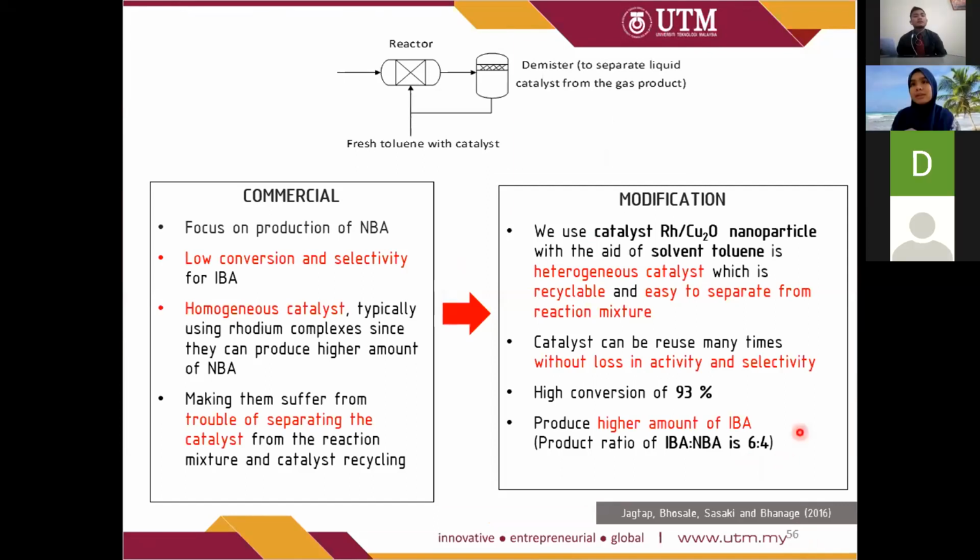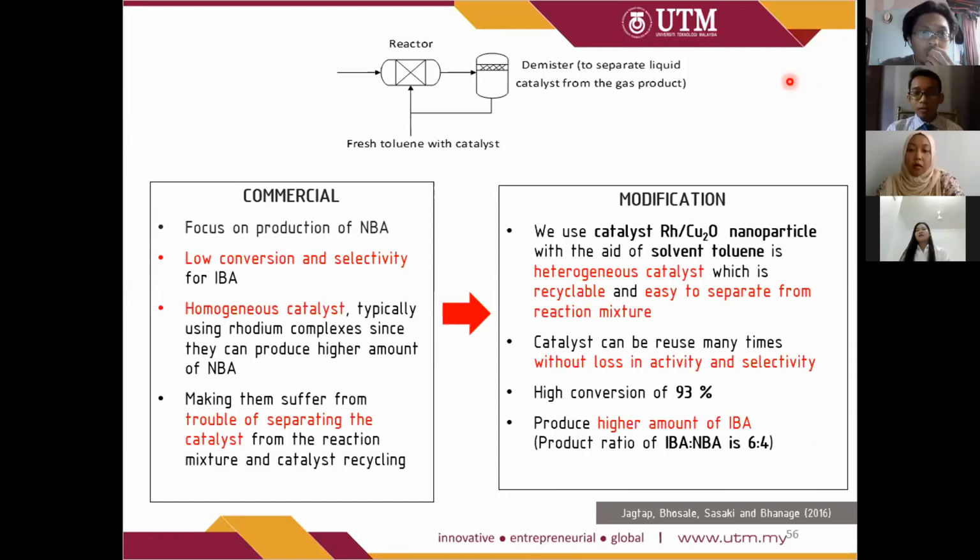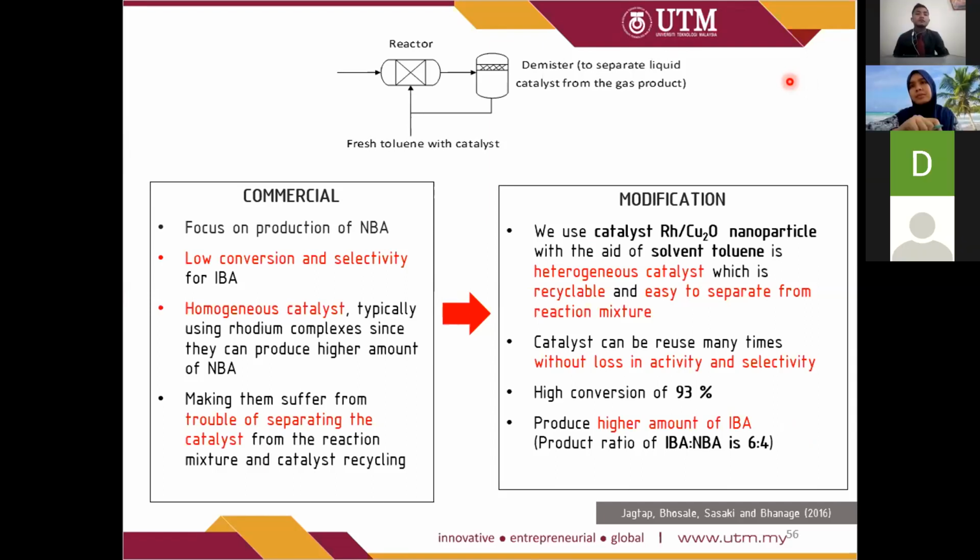Doctor? Yeah. Maybe I can add something about the innovation. Actually, the commercial one does not use the flash drum, but it uses a stripping column, so that the syngas will feed into the stripping column first, and it will recycle back to the reactor, and so on. But for us to separate our product in liquid form, it is impossible for us to make the syngas into liquid. So that's why we use flash drum instead of stripping column.